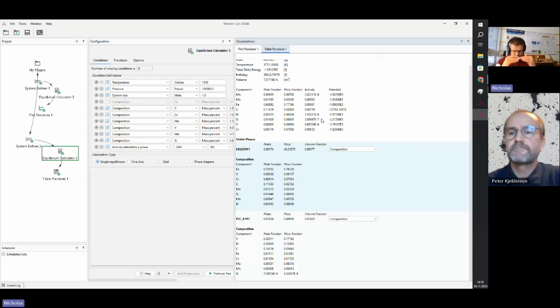You have a phase interface there, the liquid and then the gas phase. So the nitrogen somehow has to move to that interface and also through that interface to go into the steel, right? It's known that nitrogen pickup is determined both by thermodynamics and by mass transfer through that interface. It's very sensitive to oxygen or sulfur content in the steel, because these change the surface tension of the liquid metal, so how much nitrogen goes in is strongly determined by kinetics.